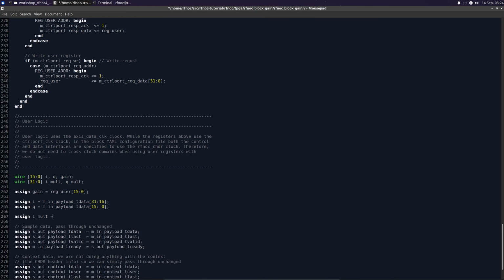And then implementing a multiply, in this case, not the most efficient implementation here, but we can just use the multiply operator. Vivado will infer a multiplier here properly. Timing-wise, it may not do very well, but let's just do this simply and use the multiply operator.